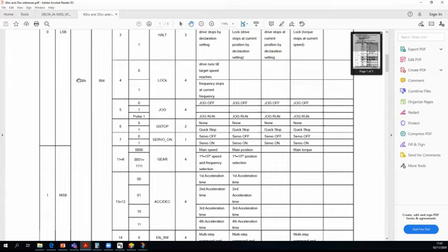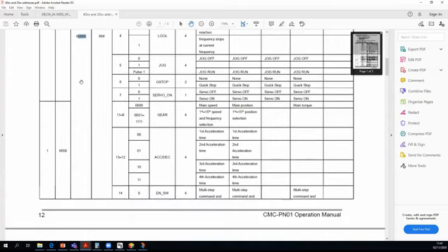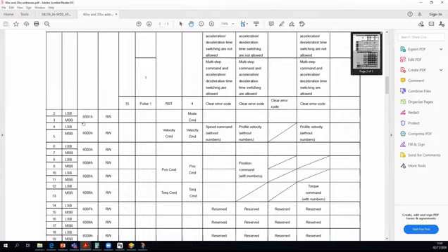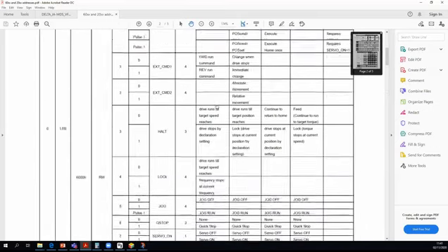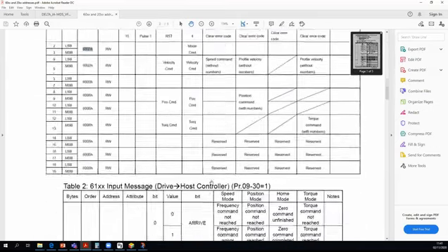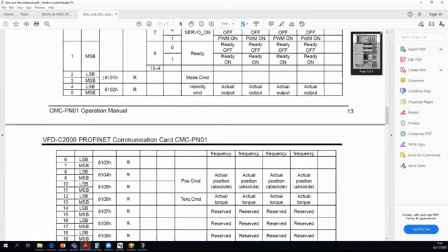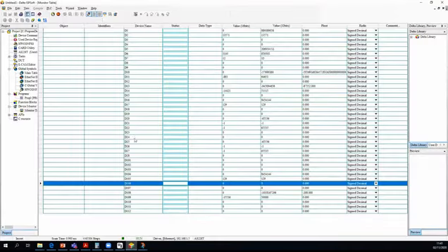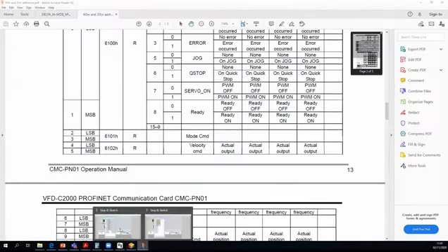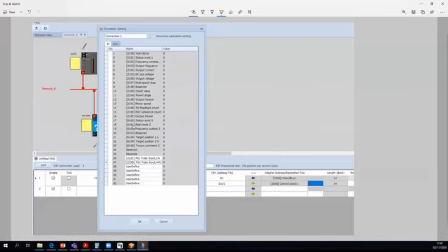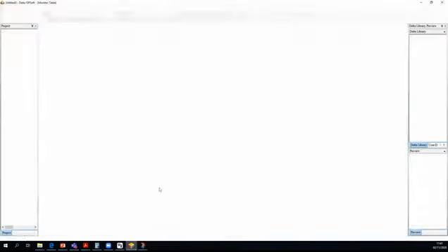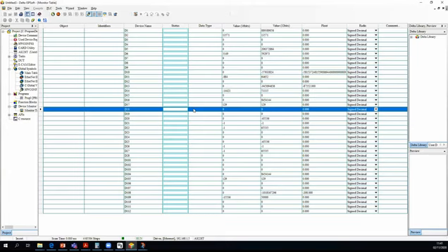If you look through the description of the different registers, you see 6000, but you also see 6001. That's the mode of operation. So 0 is velocity mode. And you can also read what the current mode is in 6001, which should be in D18. You can see here that it's 0, so that means speed mode. And I actually need to set it to positioning.